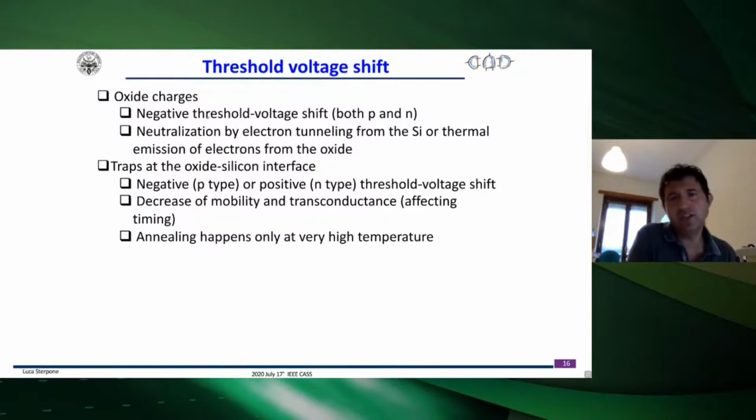This can vary depending on the particle, but the point is that you will address a different voltage threshold. On the other side, the mobility of the particles and electrons inside your gate structure, inside the FPGA, will affect the speed of the signal, and eventually might change the operational characteristics of your FPGA, for example temperature and power conditions.